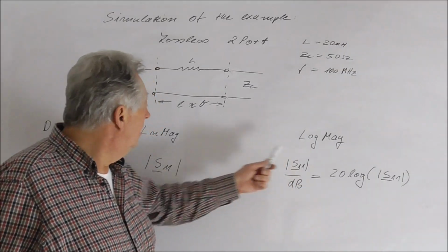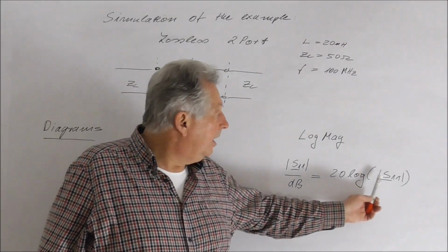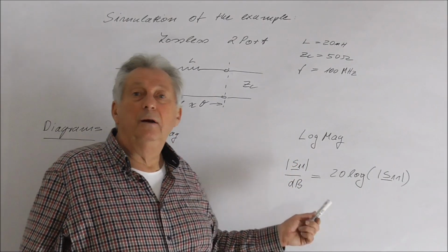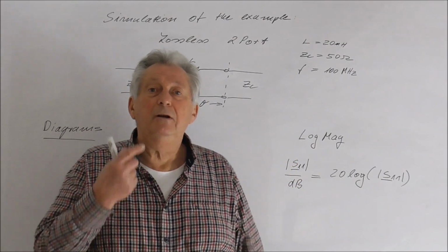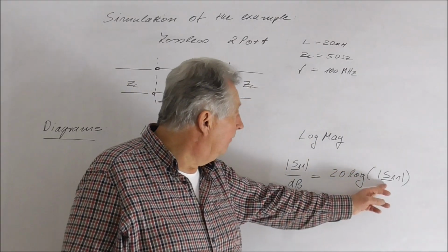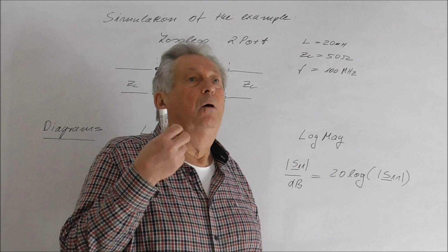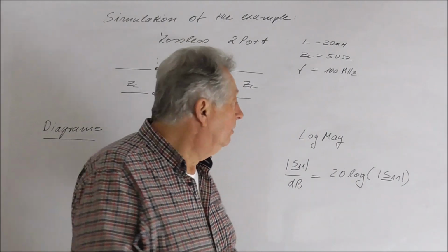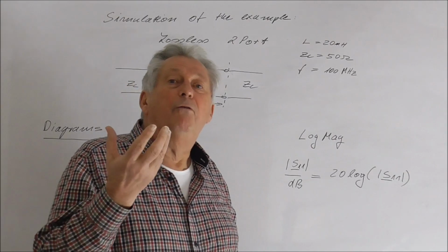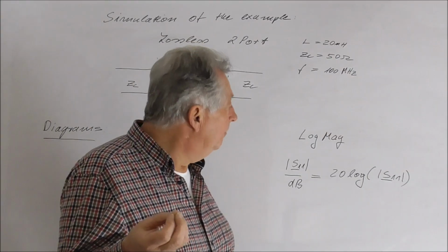we will display not the S parameter itself, but we will display 20 log S11, and then we say this is S11 in dB. Of course, from a mathematical point of view, this equation essentially makes no sense because we have twice the same value here, but I will not always introduce another parameter, so I always use the same parameter, as I come more from a physical view.